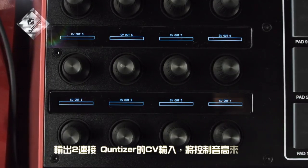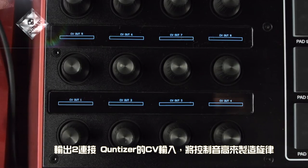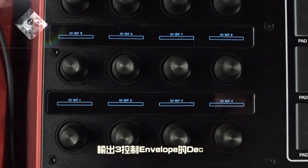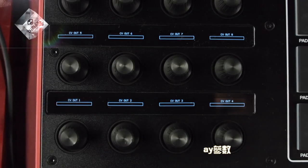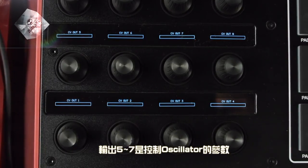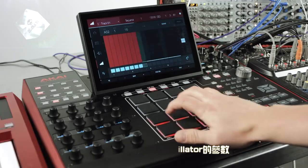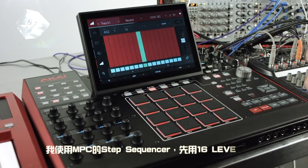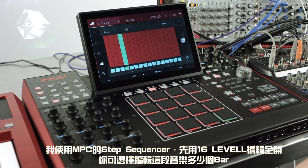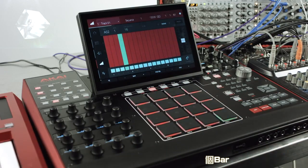Output 2 is going to the quantizer CV input. This is the voltage that will create our melody. Output 3 controls the decay of our envelope. Output 4 is our velocity, and outputs 5, 6, and 7 are controlling some of the parameters of the oscillator. I'll start by populating the step sequencer with events. I'm using a 16-step sequence for simplicity, but you can have as many bars as you like.